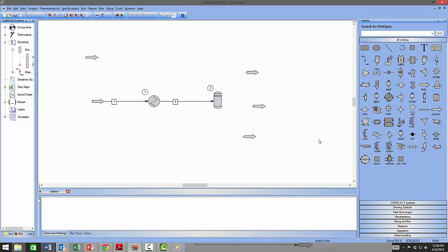Next, we can connect the gas outlet stream and the liquid outlet stream from the flash separator. This is where you can see the use of the hairline guides, how they help you to realign your connection. As you can see, for the liquid connections, there are 2 connections, the one somewhere right here and the one right at the bottom. I have used the one right at the bottom.